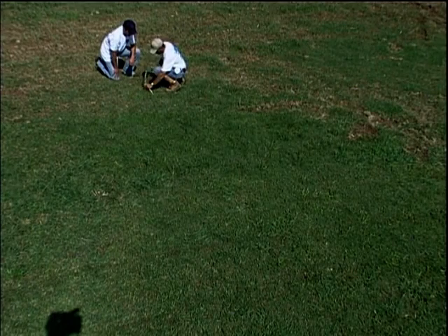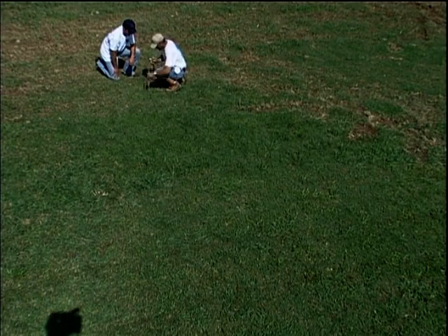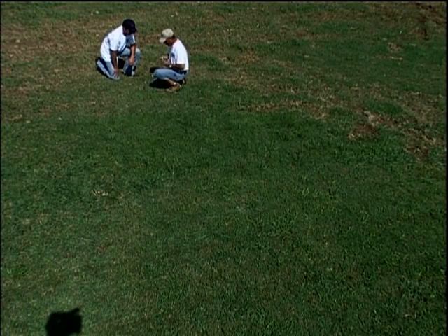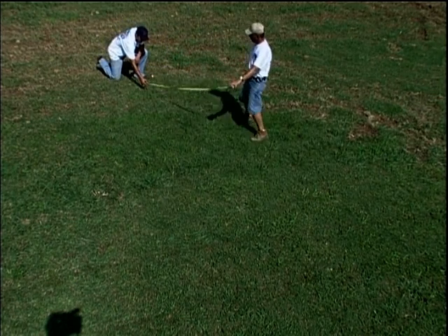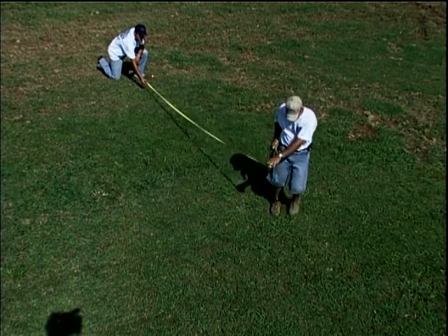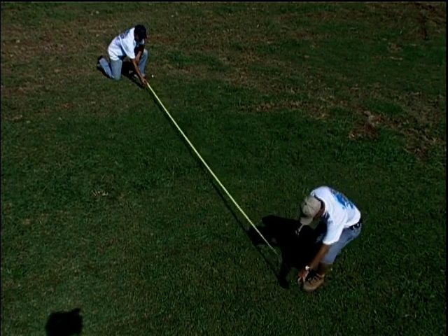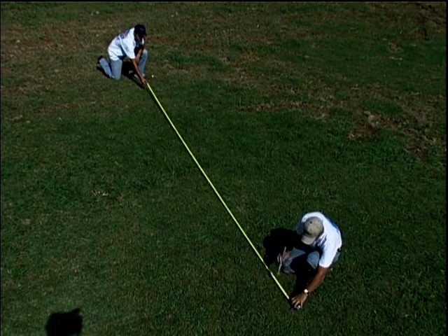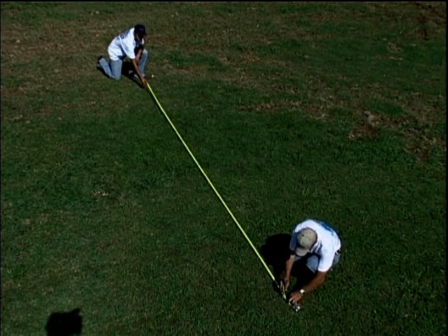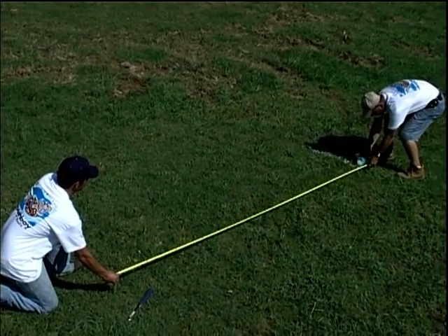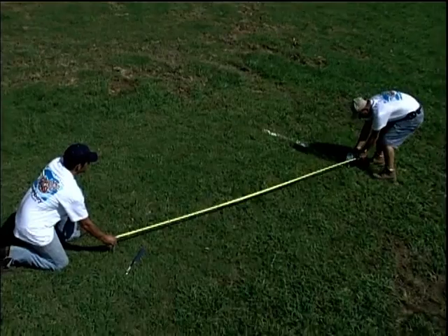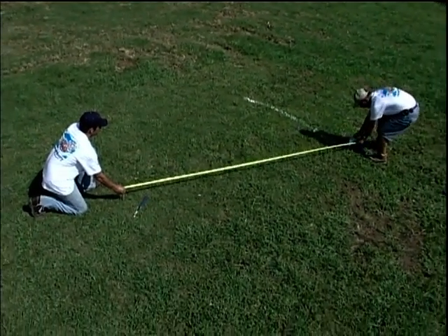When staking out the pool, be sure to allow 18 inches around the entire perimeter of the layout. This will allow a working area that will later be filled with slurry mix between the pool wall and the ground. Note, over-digging will be costly due to the amount of slurry needed to fill this area. Once you have double-checked your measurements and are satisfied with the layout, use flour to mark the perimeter that is to be excavated. This will be a guideline for the excavator.